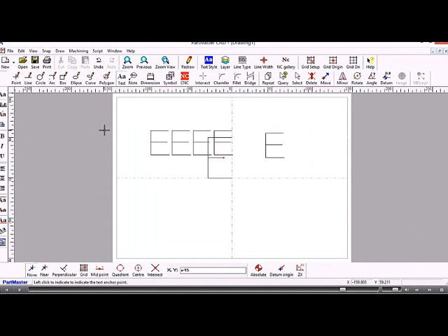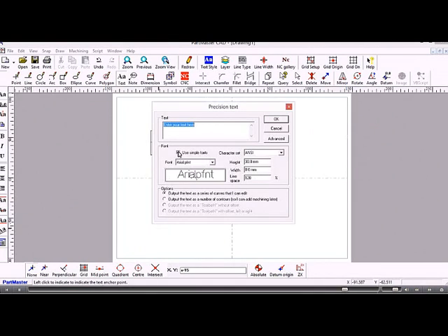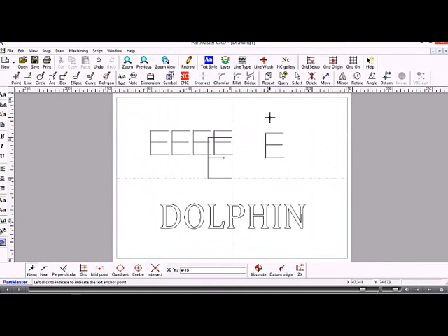The other option that we'll show you when we're creating text is if you don't use the simple fonts, you can use the Windows fonts. So any fonts that happen to appear on your system installed by Windows or any other application, we can use. The thing to bear in mind about Windows fonts is that they are outline fonts, so that you machine the outside and the inside. Within the CAM system, then of course you can do an area clearance between those. So that's how you can machine a letter E, or virtually anything, I guess.